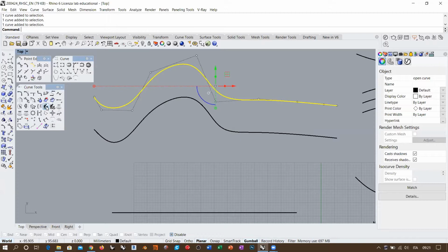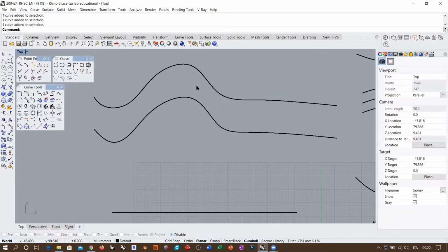Another thing is using an automatic command, which is rebuilding a curve, saying only we need 10 control points. So the command, in order to create a NURBS curve with 10 control points and a uniform knot vector, does the only thing that it can do, because there is no preference in placing the control point more in an area with respect to another one. So it distributes the control point along the curve in a uniform way, okay? It's the only thing that it can do.